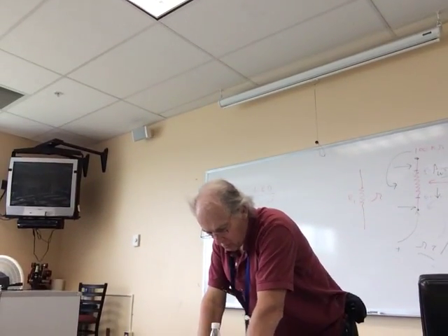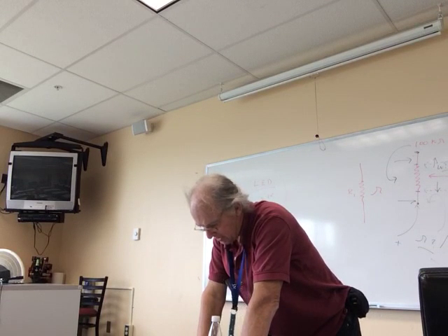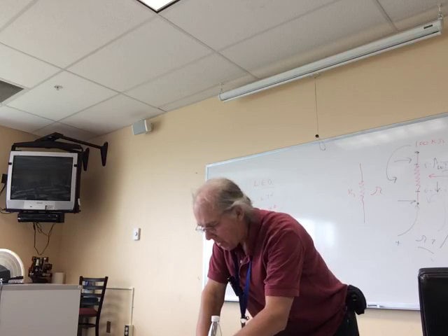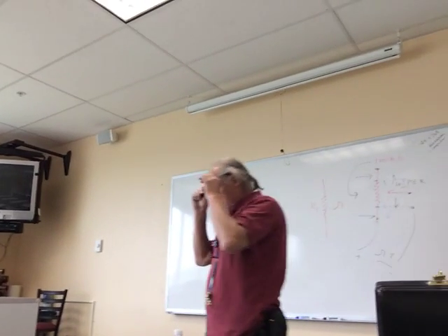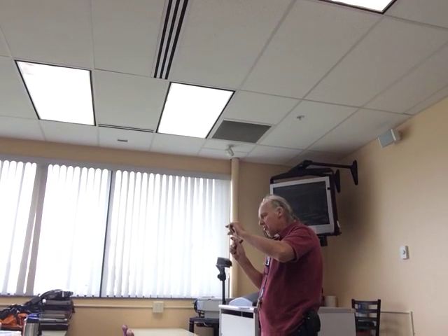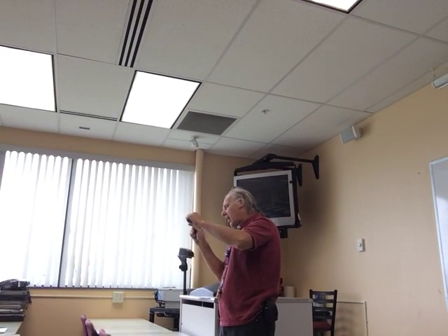Notice that they do a 4 resistor in 8-16, and they actually do the calculations, I see, and they show the current. Now, if you're going to use a voltage divider and you're going to drive a black box circuit and you know the resistance and voltage for that black box circuit, then you can tell what the current's going to be out of that black box circuit. Then you design your voltage divider to give you the proper voltage by placing that in. You say, okay, I got a parallel resistor, so I know what size resistor here will give me the proper voltage so I get current through the black box to make it operate, okay?